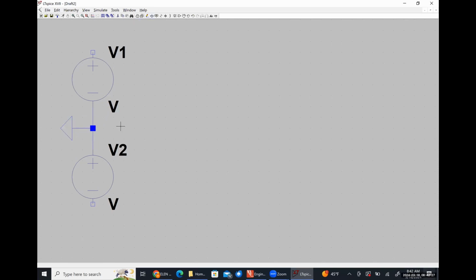Okay. I'm not required to do this in LT Spice, but this is physically what I would do in the lab to implement a positive and negative voltage from a single supply, right? This is exactly what we did in circuits 1 for our op amp lab. It's what we'll continue to do the entire time we're here. So this voltage is going to be 5 volts, and this voltage is going to be 0 volts. Now, I know it seems weird that I'm including a 0 volt source here. I'm just doing a kind of best practices type thing.